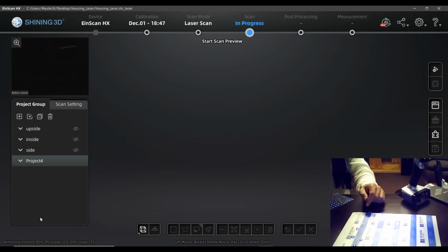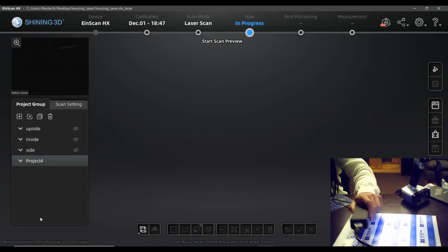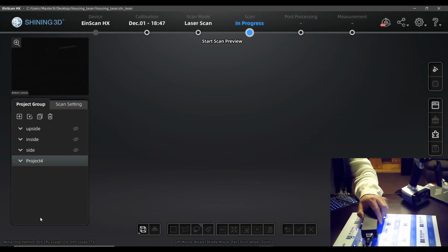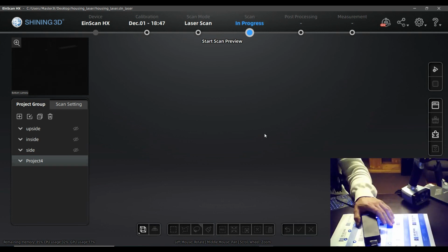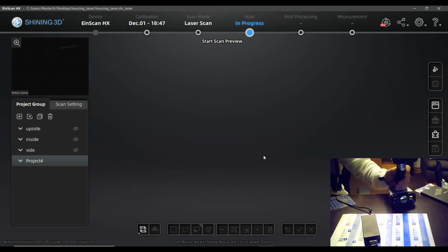So if you are having a part that's not too high and you have enough positions that you can capture, always looking to the downside of the scan set, it can be really enough just to put markers on the surface that you are using as ground.